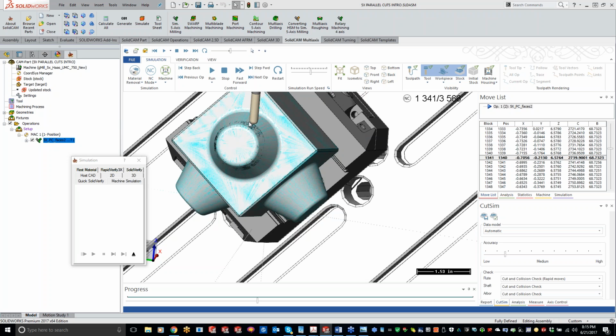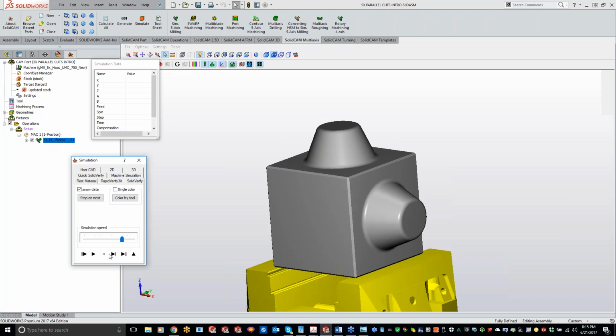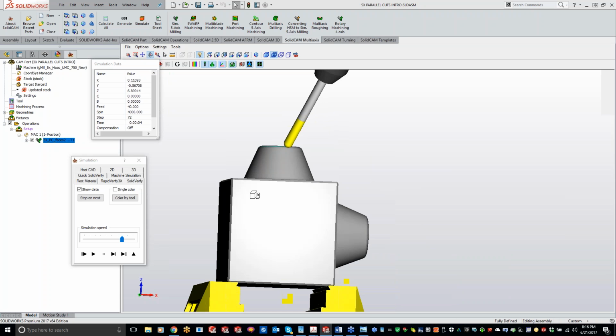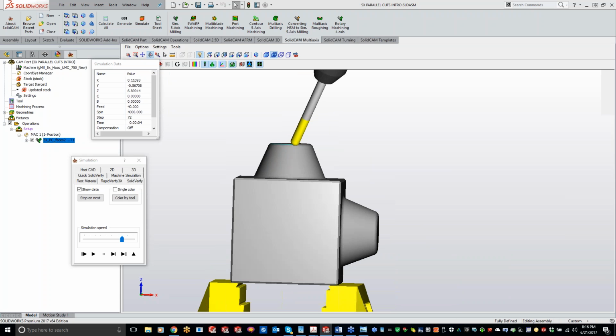And like I said, more personal preference, but I really think you guys get a much cleaner, nicer finish when you're using the side of the cutter versus the tip. Let's do a solid verify real quick here. I'm just going to hold my space bar here so we can see, let me get control here. There is a good representation of kicking that over at 20 degrees right there.